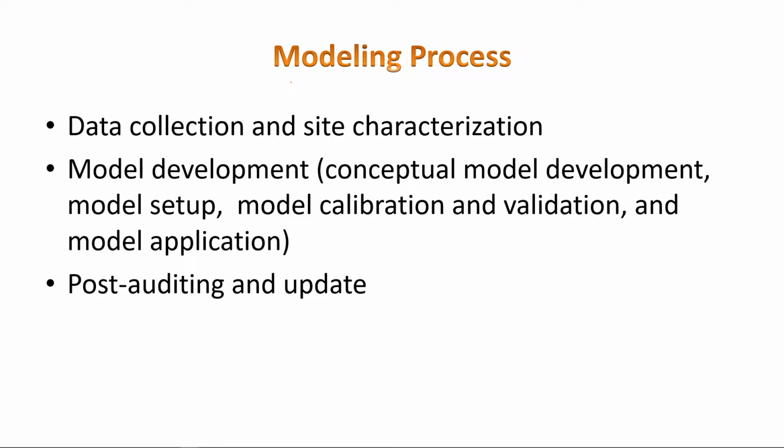And modeling is very important in groundwater hydrology because we deal with natural systems that are vast. I cannot get an aquifer and study it in the lab, unlike other things where you can get samples and study them in the lab. Aquifers extend spatially by kilometers, tens or hundreds or even thousands of kilometers, as we've seen with the Nubian sandstone aquifer. So the way to study and manage these aquifers is that you create a model, you bring this model to your computer.